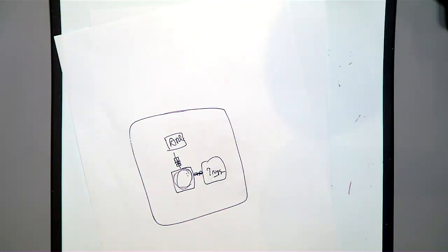So if possible, maybe this will not be possible with your complex innovation, but at least you can reduce the risk by putting a footprint of a 0 ohm resistance, so that you can test your DSO working without your innovation part. Then when it is working, you can introduce the innovation by shorting something. That is a good idea, so that you make sure your DSO design is not affected if something goes wrong with the innovation.